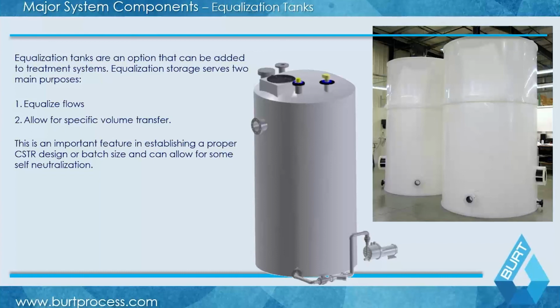This is where an equalization tank makes sense. You transfer that larger volume into an EQ tank, and then you transfer to your system, if it's a flow or hybrid style system, at that more continuous flow rate, as opposed to oversizing your system.